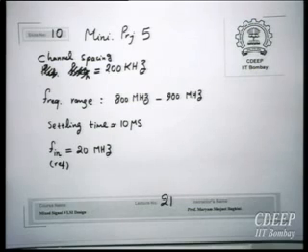There is one way. If it is an integer, that's why I didn't talk about the prescaler, it means that you will have divided by N, an integer. But if you have a rational number, say for example M upon N, then it is possible. So one thing we can do to make it easier is to make the channel spacing 20 megahertz. That is easier. Then your counter also will be smaller. You make the channel spacing 20 megahertz, no problem.